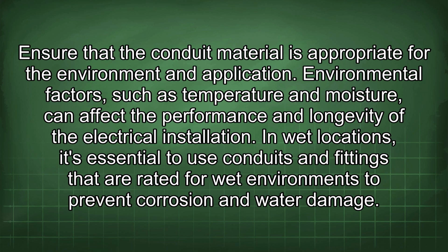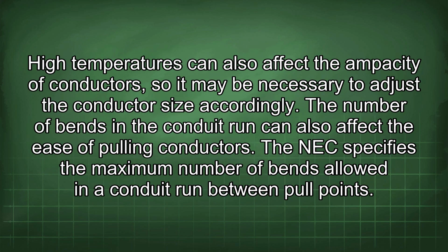Environmental factors such as temperature and moisture can affect the performance and longevity of the electrical installation. In wet locations, it's essential to use conduits and fittings that are rated for wet environments to prevent corrosion and water damage. High temperatures can also affect the ampacity of conductors, so it may be necessary to adjust the conductor size accordingly. The number of bends in the conduit run can also affect the ease of pulling conductors.